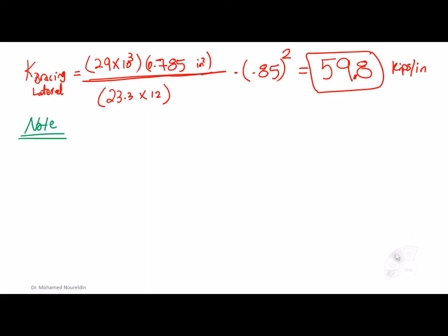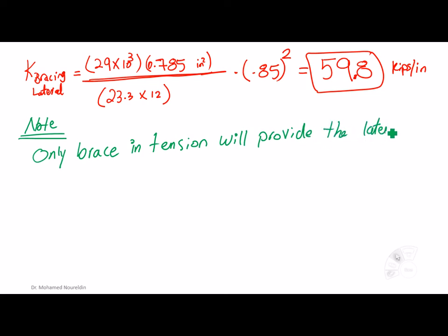So we need to put it as a note here, and we are going to say only brace in tension will provide the lateral stiffness of the braced frame.